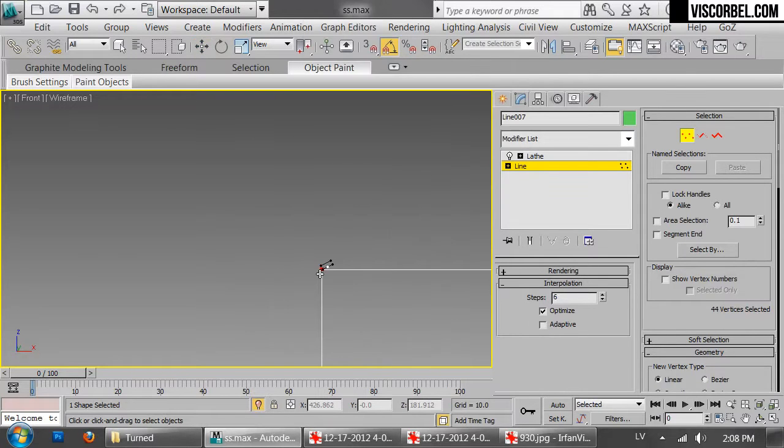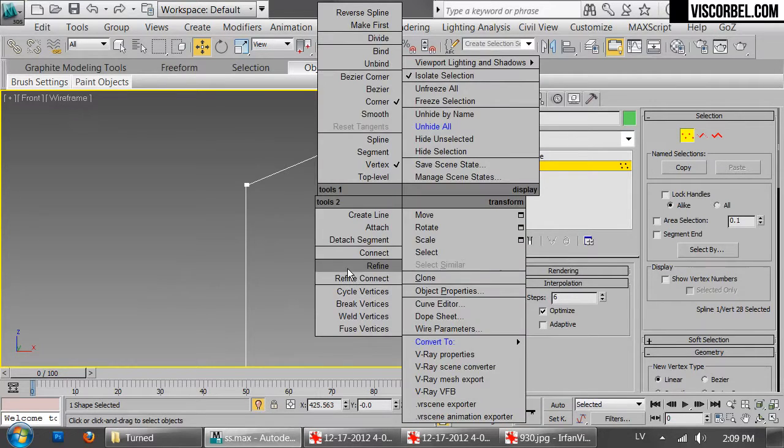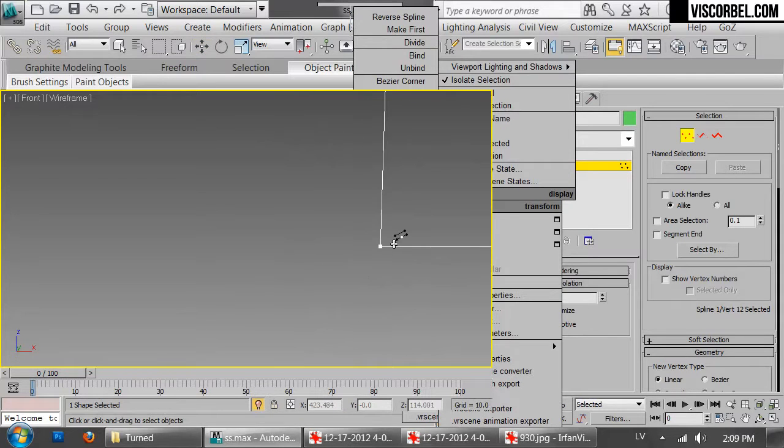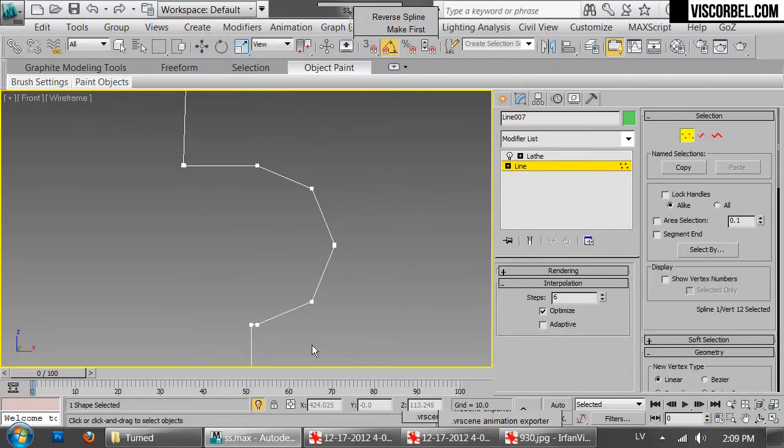after the turbo smooth modifier. So a couple of support vertices here, here, and here as well. Okay, that's a bit weird, but alright. Again, just add some vertices everywhere you want hard edges after the lathe and turbo smooth modifiers. Just go over it quickly.